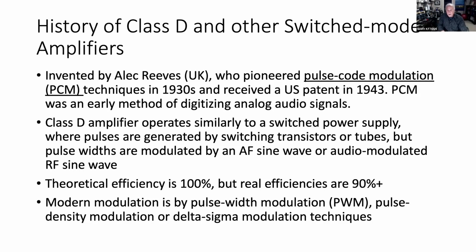The idea is that when you have a switch mode power supply or amplifier, and there's really very little difference, the efficiency is extremely high because the transistors generate very little heat during the switching process. When they conduct current, the voltages are very low because they're in saturation mode. In saturation mode, the voltage across the transistors is low, but they're conducting a lot of current. So the power actually being dissipated is very low. So there's very little dissipation of heat.